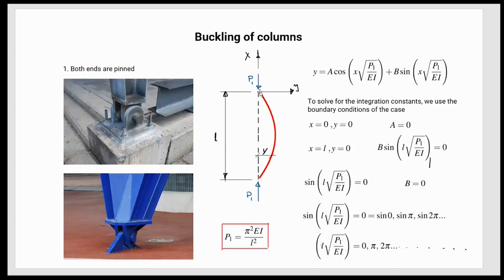Instead of having restrictions for relative movement between the column and the other element, you are saying, you know what, if you use a pin end, this column would be able to rotate around these connection points. If I let go of the upper part of the column, it's going to rotate towards one end or towards another end.